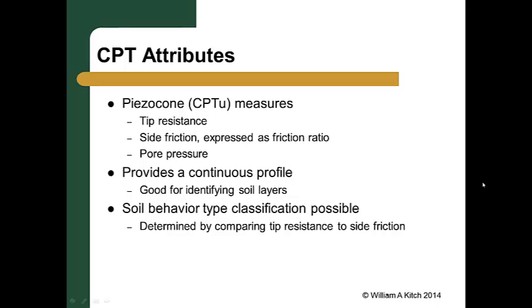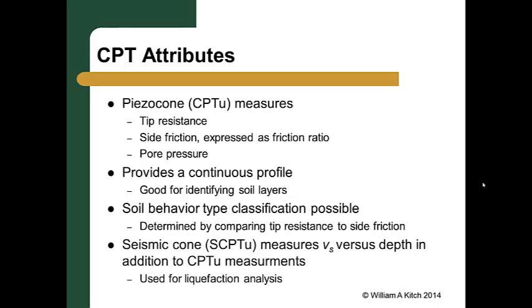We can use this profile to classify soil based on behavior by comparing the relative magnitudes of tip resistance and side friction. The seismic cone measures shear wave velocity versus depth in addition to the measurements made by the piezo cone. Although this is a topic beyond the scope of this presentation, the seismic cone is particularly useful for liquefaction analysis.